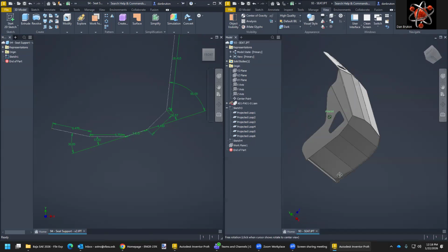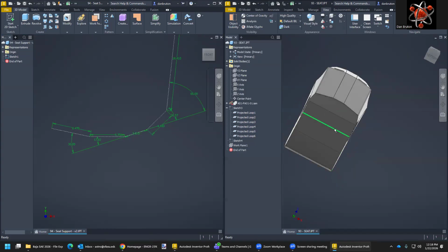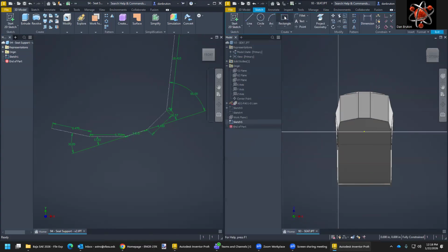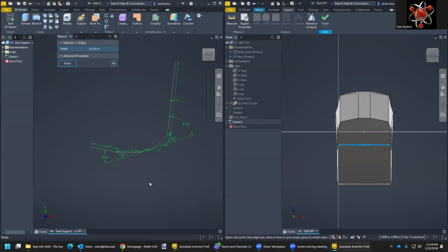Let's just get it to be around the bottom right here first of all, and then we'll figure out how to do it that way. So looking at this piece right here, we can right click, new sketch to figure out how big it is. And so we can say inspect, measure, and the entire width of this right here appears to be 15.3. Okay, so let's just try to break it up and say, let's just go 5 inches in from each side to see if that works.